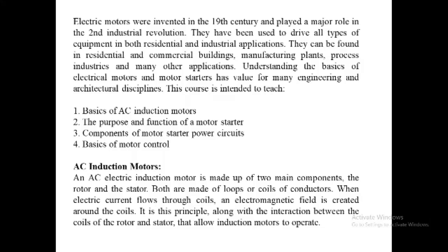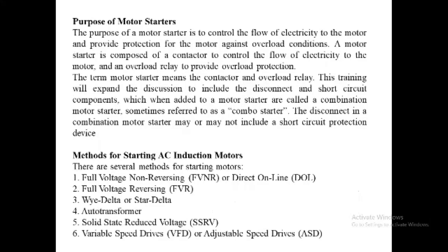What is the purpose of the motor starter? The purpose of the motor starter is to control the flow of electricity to the motor and provide protection for the motor against overload conditions. A motor starter is composed of a contactor to control the flow of electricity to the motor and an overload relay to provide the overload protection. The term motor starter means the contactor and overload relay.